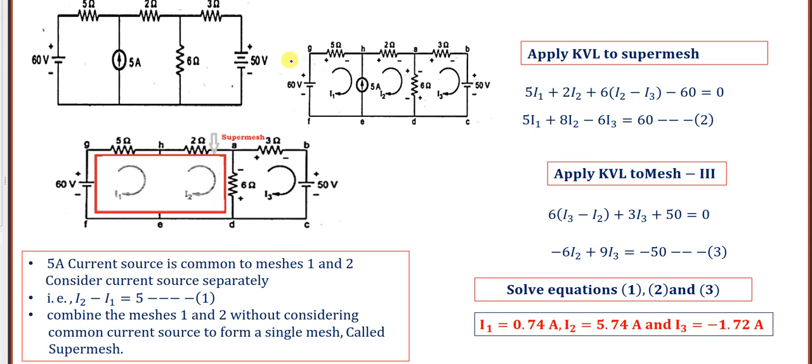Now I have to apply KVL for this. I know this is a voltage source of 60 volts, and here the current I1 into 5 ohms is the voltage. But while writing KVL, I don't know what is the resistance of this current source, so I cannot apply KVL for mesh 1. Similarly, while writing KVL for mesh 2 also, I don't know the resistance of this current source. So I cannot apply KVL for mesh 1 and mesh 2.